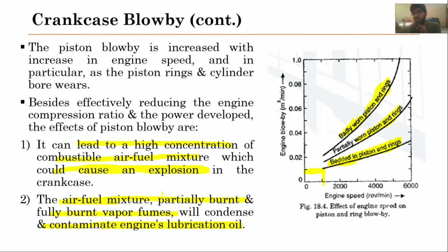You must have seen that when the piston rings in your car wear out, it will start consuming the lubrication oil as well. The lubrication oil will come into the combustion chamber and the exhaust gases will flow back into the crankcase, into the lubrication oil, which will contaminate it and change its characteristics, and that lubrication oil will not provide the desired amount of lubrication. So these are some of the disadvantages of the crankcase blow-by.